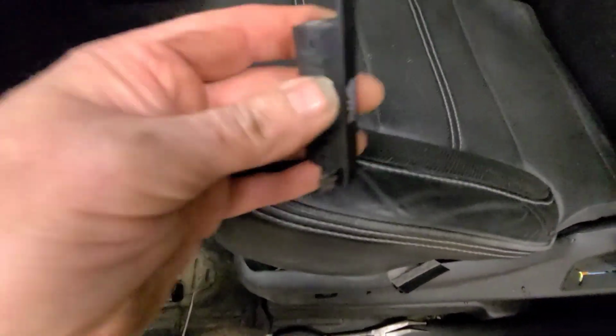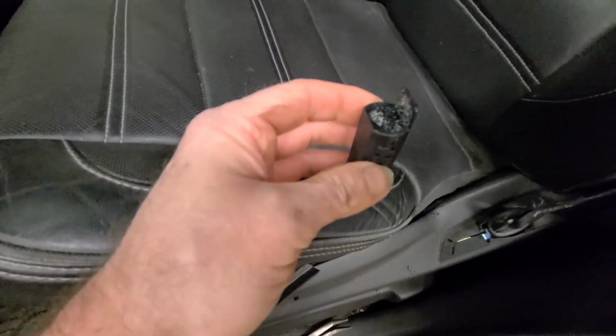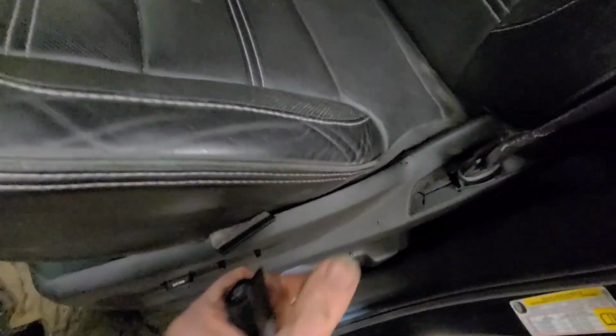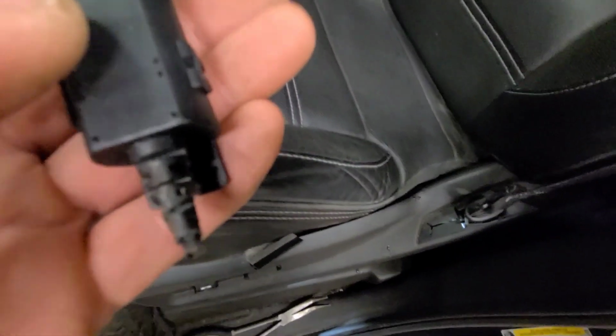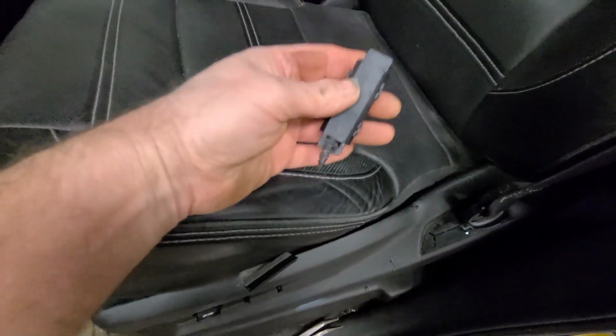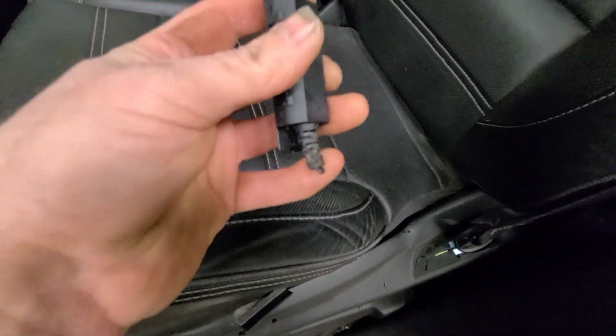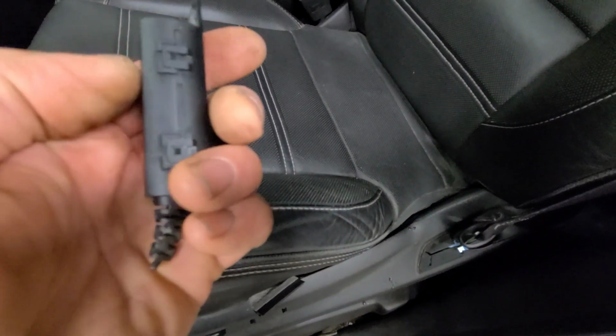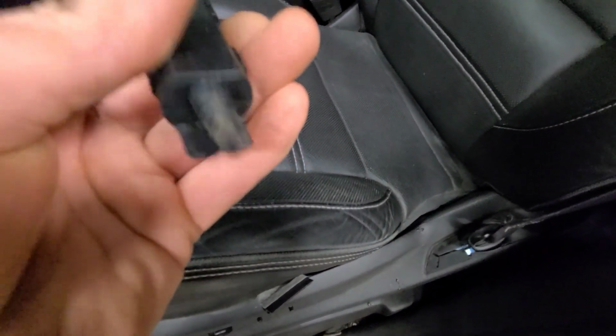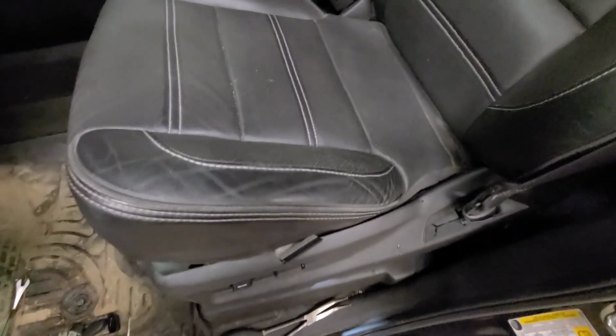So there's the motor. It just pulls out of a little pocket in the seat, sits up like that, right in this sponge. And of course, every time you get in and out of the vehicle, it pushes down on the sponge and flexes these wires. How the engineers couldn't realize that that was going to cause the wires to break. Now to fish the connector out, that's going to be fun.